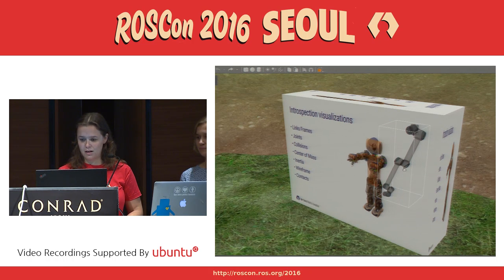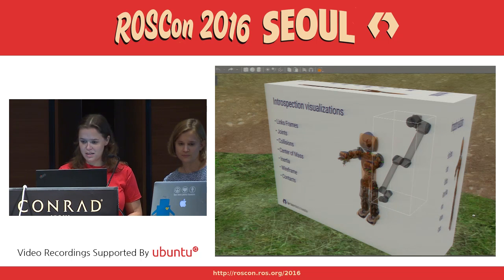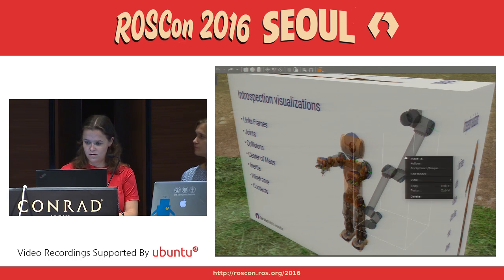And then I'm gonna take a look at the joint frames, at the link frames, which are basically the origin for each one of the links. So you can see that these frames, the red, green, blue lines, show the frame for each one of the links. And as you click on them, they highlight so you can quickly associate the link to the origin of that link. And you can quickly see, oh, I have the wrong axis, that's what was going on, or I have the wrong sign.